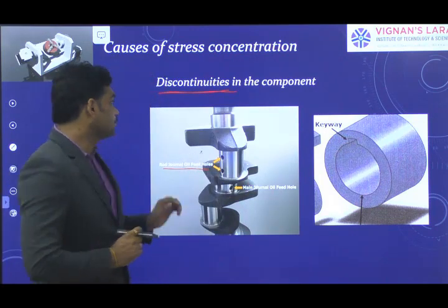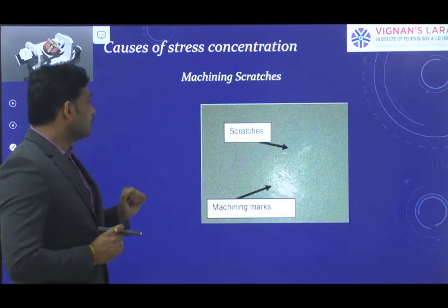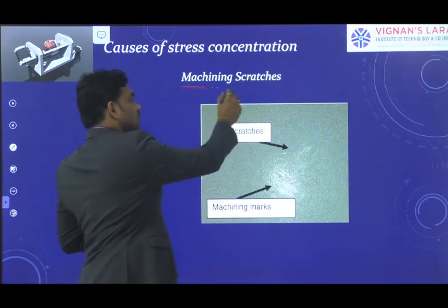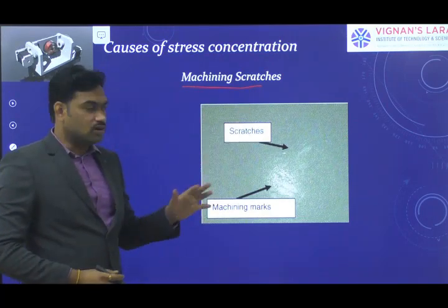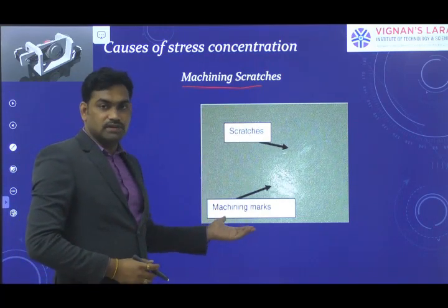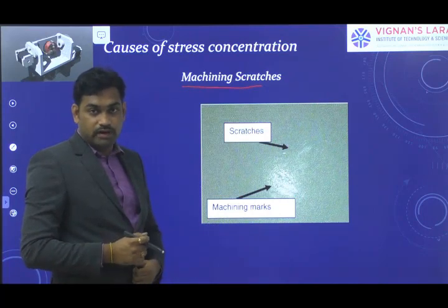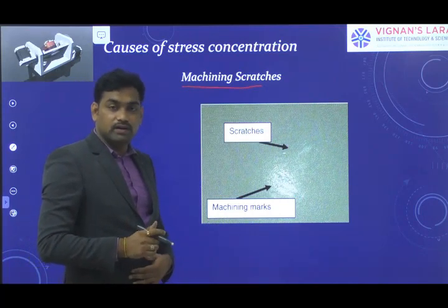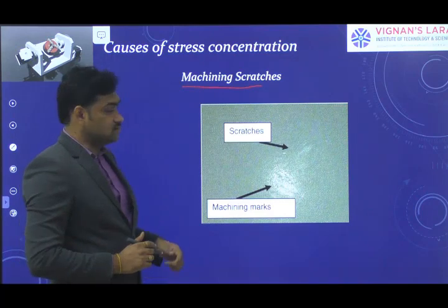So let us see. This is also one of the causes of stress concentration: machine scratches or machining marks or indentation you can provide upon the component. It can also raise stress concentration.